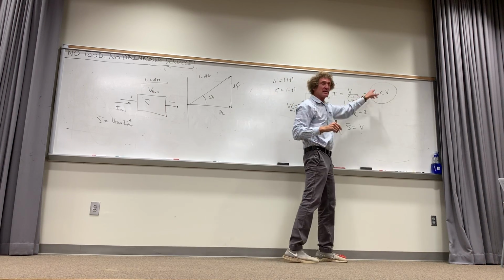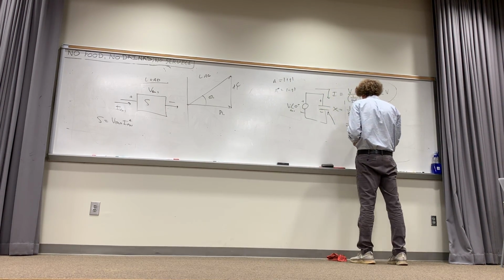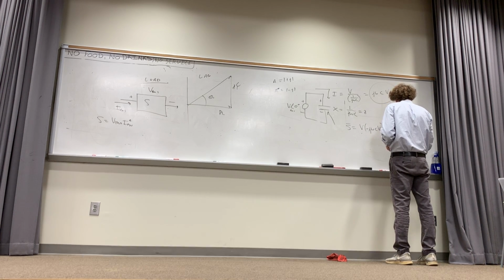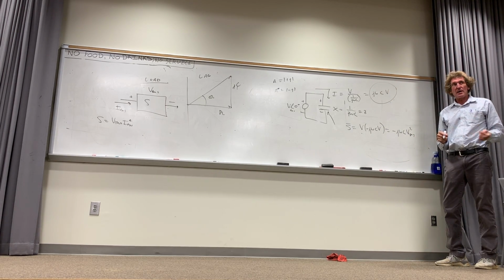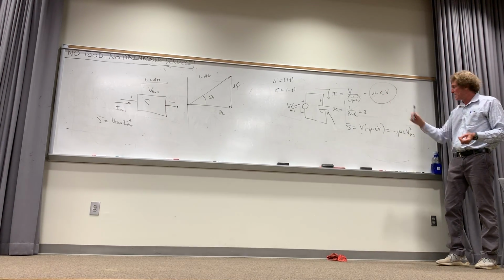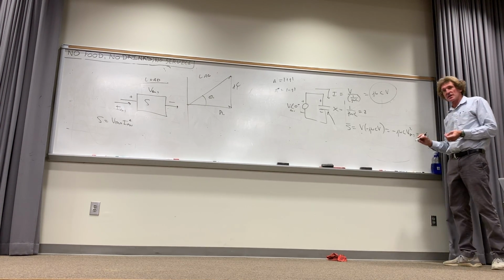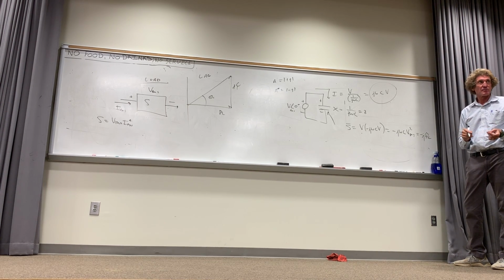So wouldn't this be just minus j? Because there's 0 in front of it, right? Sure, so it'd be this times minus j omega C times V. And you can see that's minus j omega C times V squared. And that's V RMS too. Make sure you understand that. So the complex power associated with that capacitor is really going to be equal to minus jQ, isn't it, class? And you could put it jQ sub C, indicating it's a capacitor. Everybody follow me? How many see this right here?